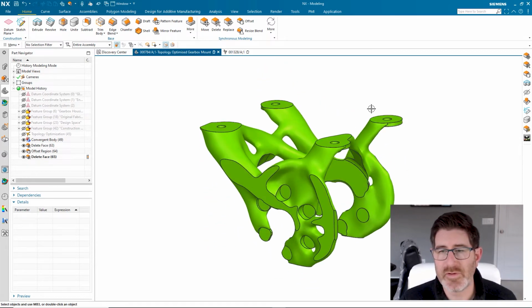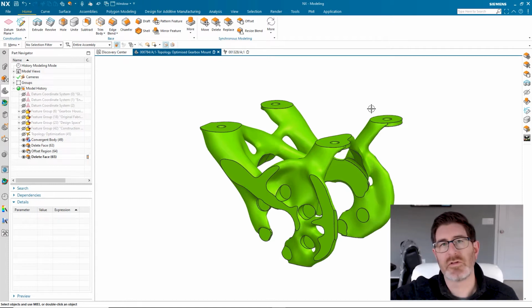The final step is down here on the bottom. We have these 4 sort of feet, and we want those to be all perfectly planar so that when we mount this in the car, it's not going to wobble, it's not going to torque and have any undue stress put on it. We want those to be perfectly planar.